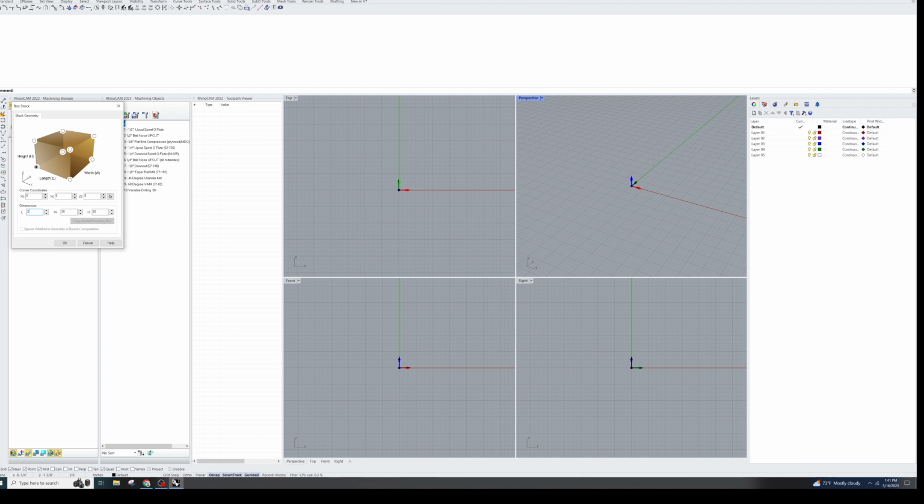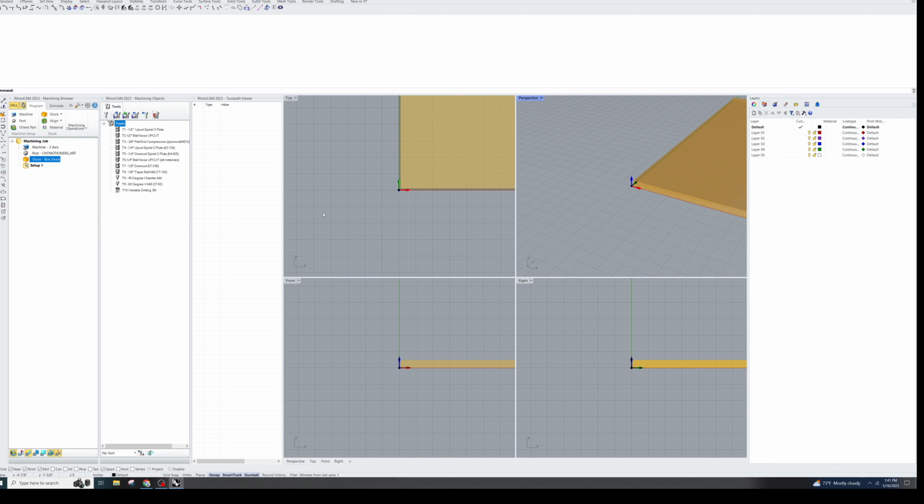So if my stock is 25 by 25, and the thickness is the height, I want to use calipers to measure that exact. So even if I bought 1/2 inch stock, I want to make sure it's exact. So it might be 0.48 for this example. So I'm going to use it, and you'll see that the thickness view is here, and it shows up in the corner.